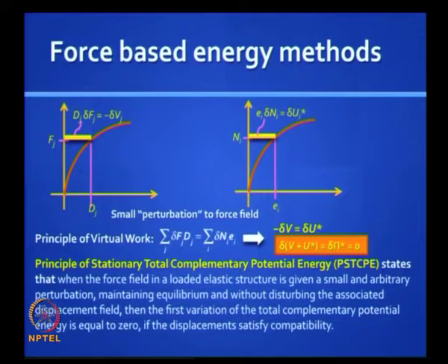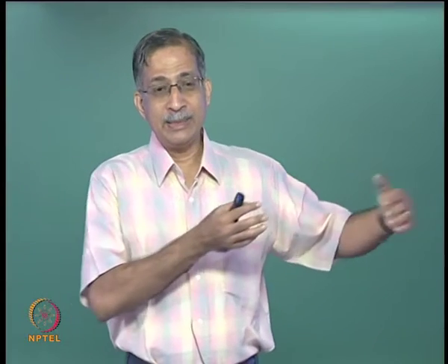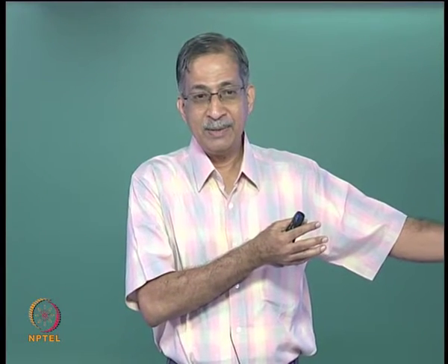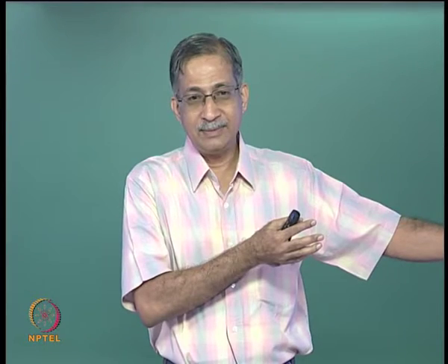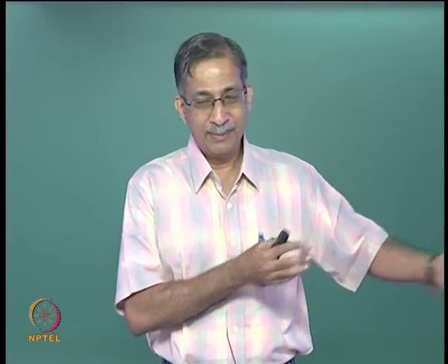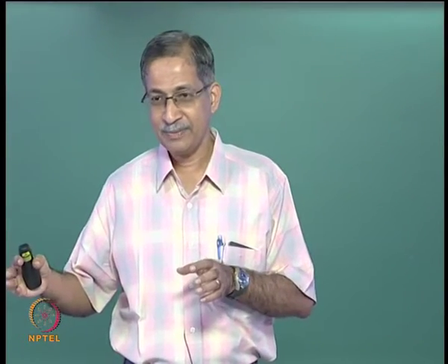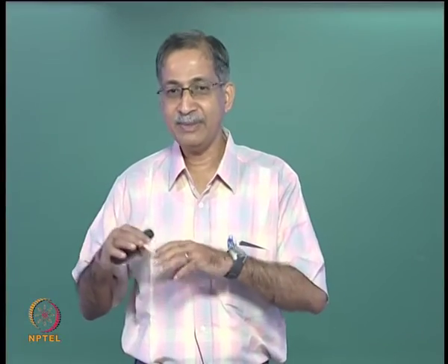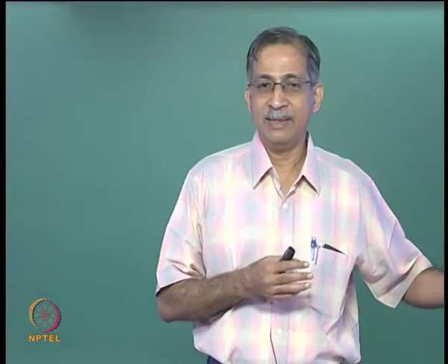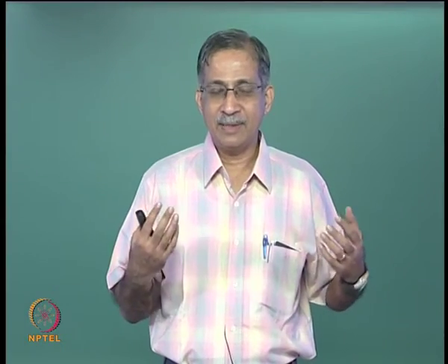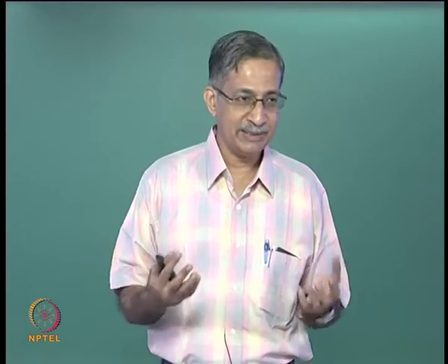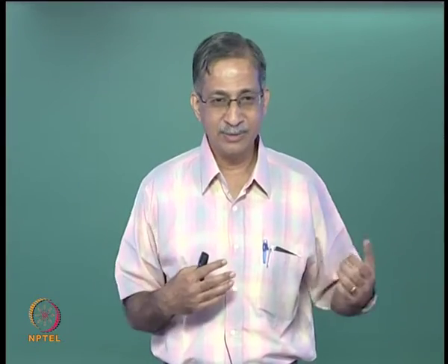The format is the same, but there you are disturbing the displacement field. Here you are disturbing the force field. When you are disturbing the displacement field there, you are not changing the forces. When you are disturbing the force field here, you are not changing the displacement. So that is important to note. It is something you do in your mind. It is arbitrary and of very small value, and the cause that you refer to here is perturbation and the effect is variation. Those are the terms used.